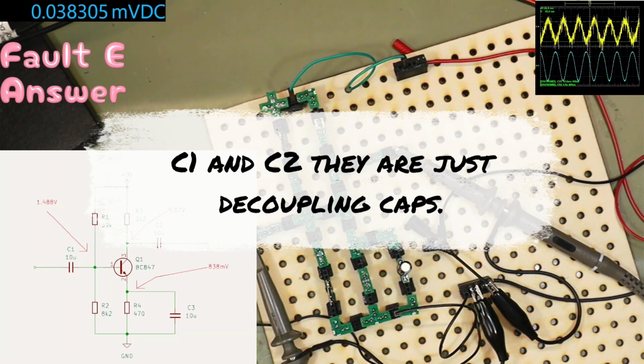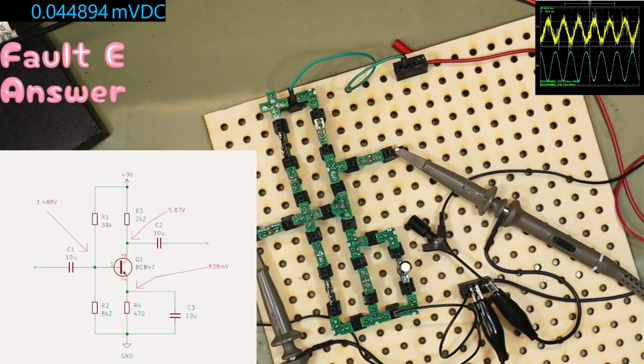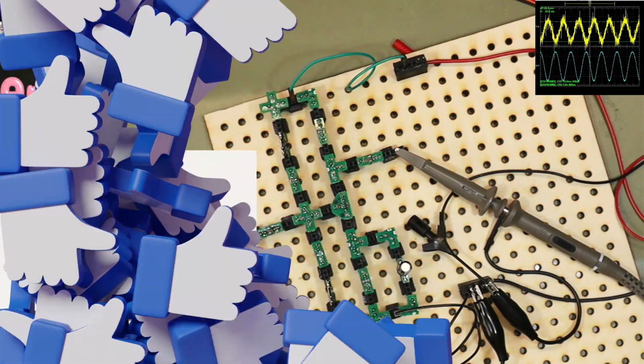You know, if they die, then you might put a DC condition on here, and it will drag it down. If it goes open circuit, there's no signal. Open circuit, no signal. If it's short circuit, then whatever happens here is totally dependent on what the DC conditions are on this side. So that DC voltage will just get dragged somewhere. But then you just measure across the capacitor, and if it's exactly the same on both sides, DC-wise, you've got a short.